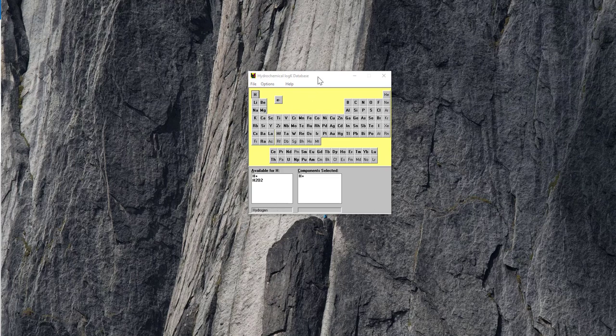This is the interface for the Hydra component of the software, and the Medusa is a separate package that's used for plotting. So Hydra is really just an interface that collects all of the log K thermodynamic data related to all of the different elements on the table. And so if you're interested in modeling speciation for a particular species, for this example we'll do the carbonate equilibria, so carbonic acid in equilibrium with water, then we would think about the element that uniquely comprises that species. So for carbonate, that's carbon.